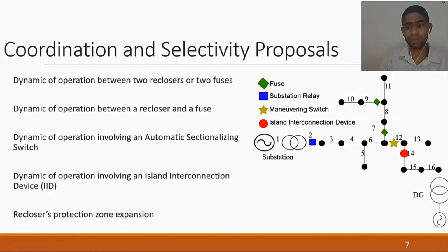The recloser must operate in instantaneous operation faster than the fuse, but in the delayed operation, the recloser must be slower than the fuse.